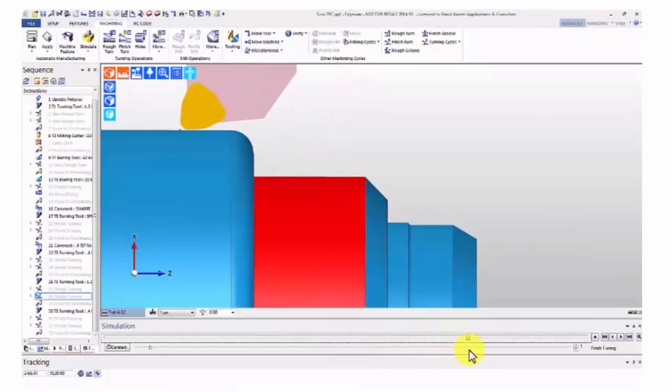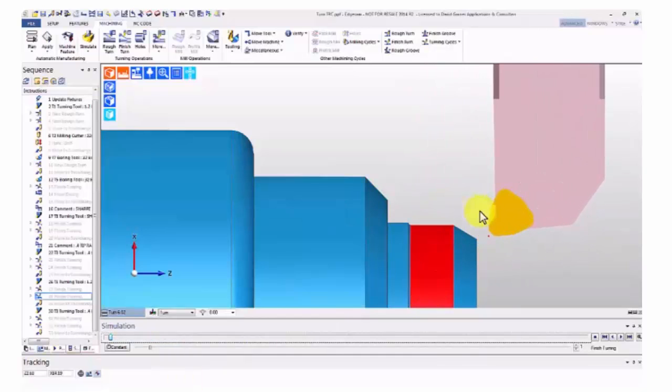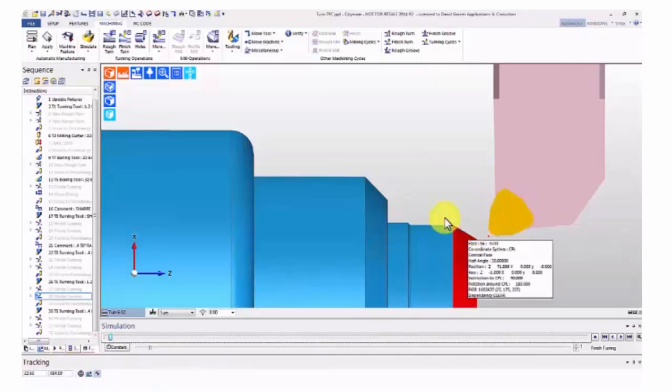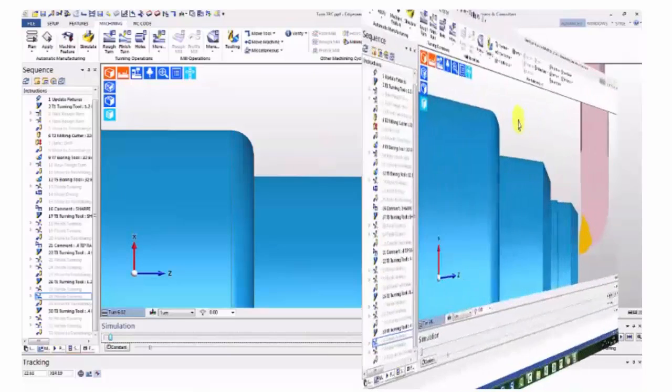Now for most components that probably doesn't matter, but where it starts to get awkward is if you want to change the tip rad. You might modify these chamfers to get roughly what you want. The rads will be wrong, but you're probably living with that. But if you wanted to change that rad, then effectively the path will change again. So that would obviously cause you a problem.